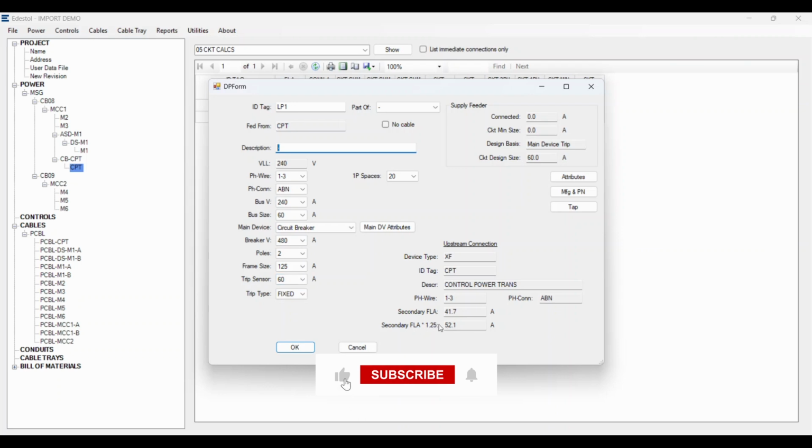You would run a 50 as your main, not a 60. So 50 would actually be considered some sort of a tap, since you connected a distribution panel directly to the transformer. It sizes the breaker as the next size larger than your max secondary FLA times 1.25. But we really want it to be 50. So that technically is going to be a tap where you're doing some percentage less than full load. So this is what you would run if it was full load.